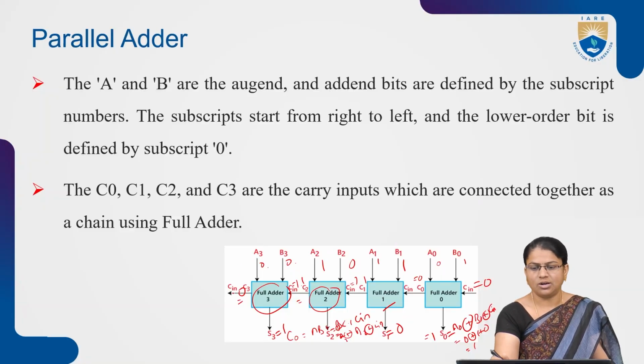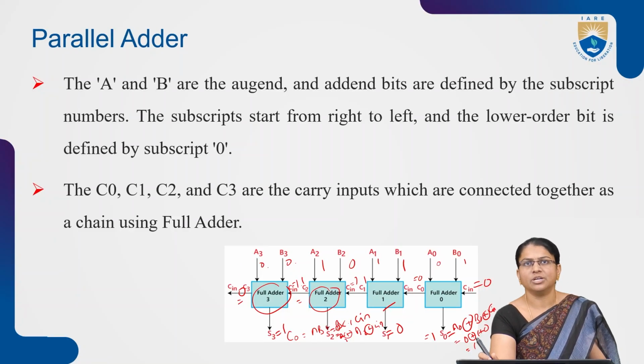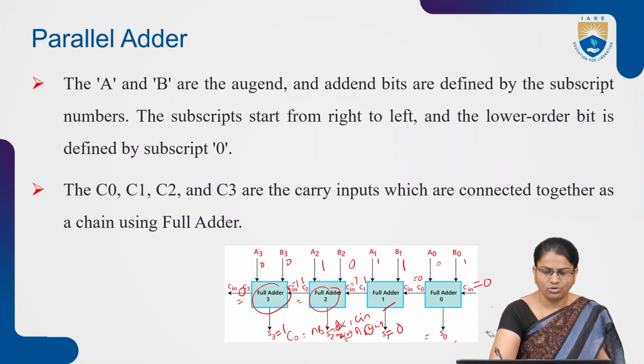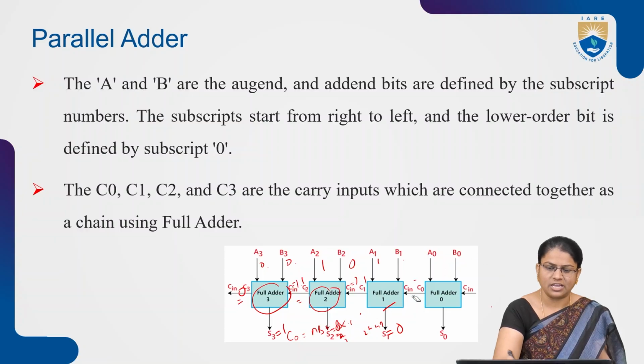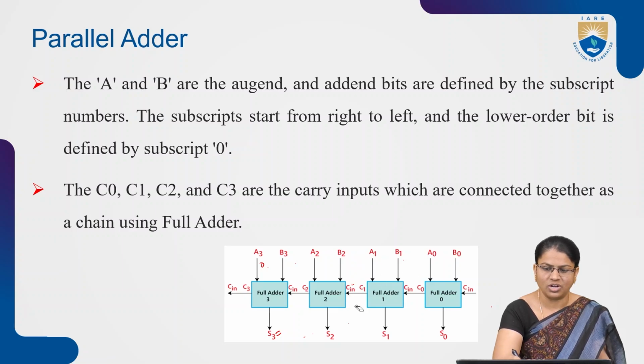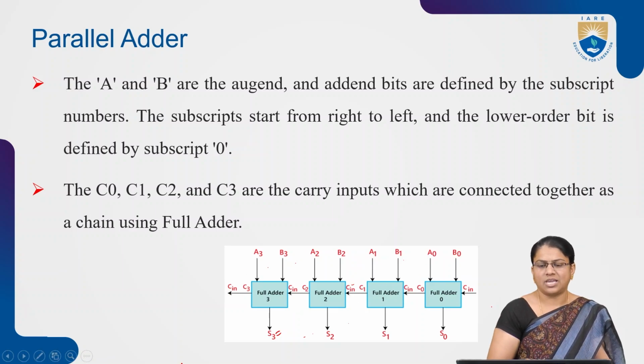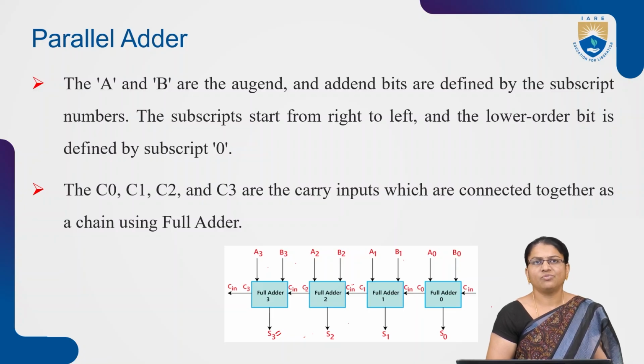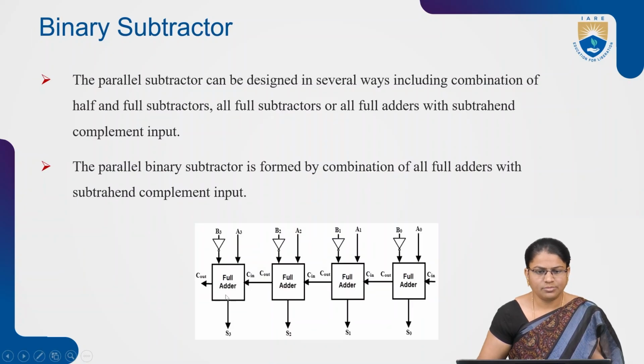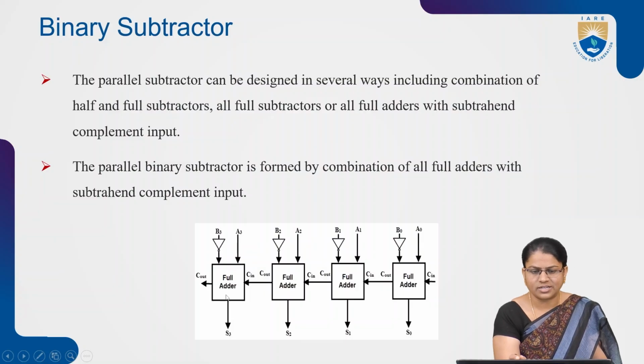So this is the operation that takes place by using the parallel adder circuit when we want to calculate the sum and then the carry equation for the full adder. In case of the sum equation, A XOR B XOR C is the sum equation for the full adder. How the next carry outputs are generated, that acts as input to the next full adder circuit, right? So this is nothing but the normal full adder circuit.